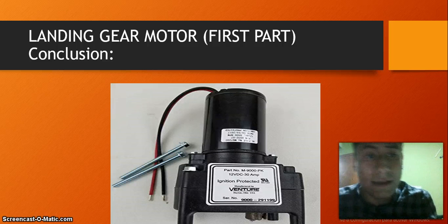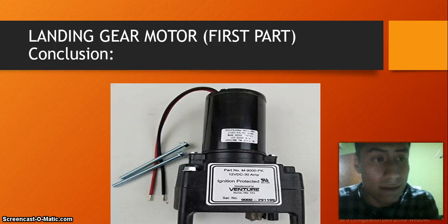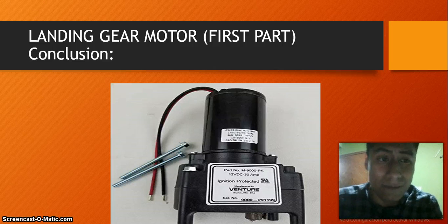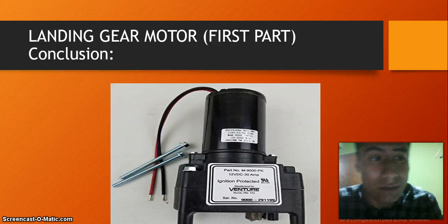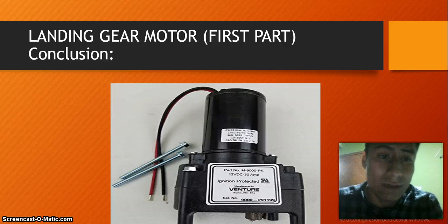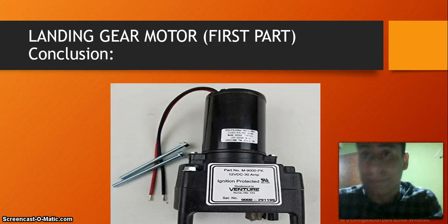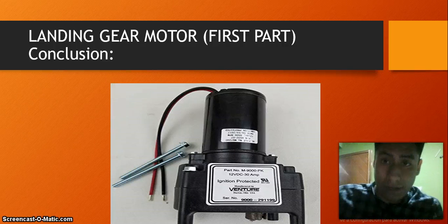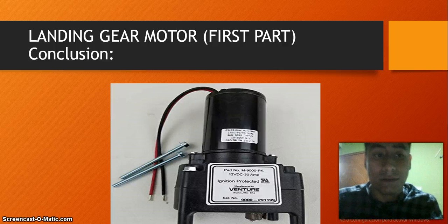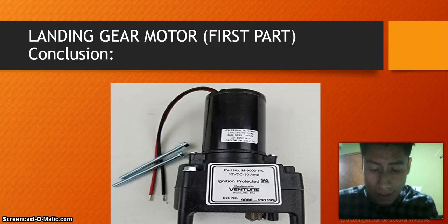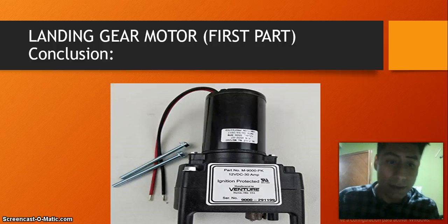When the landing gear selector on the instrument panel is placed in the down position, it operates the motor and the retraction transmission. The transmission pulls the torque arms back, which pushes the main gear cables and the nose gear tube, extending the landing gear. When the gear is fully extended, the gear down switch stops the motor and the green gear down and locked indicator light on the instrument panel lights up.